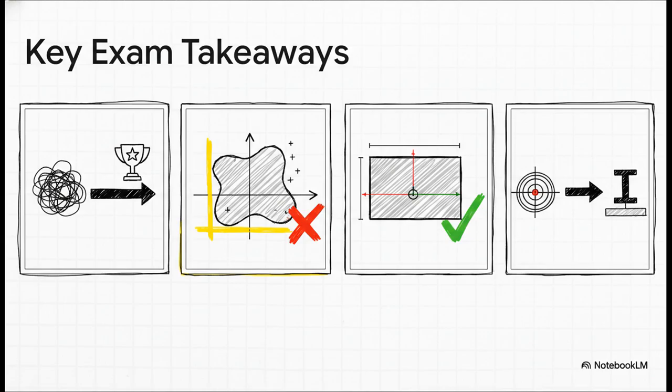And be really careful about the most common mistake. Always measure the perpendicular distance from the centroid of each small shape all the way back to your chosen reference axes. And finally, why is this all so important? Because mastering the centroid is the essential first step to understanding the next critical topic, which is the moment of inertia and concepts like the neutral axis in beams.